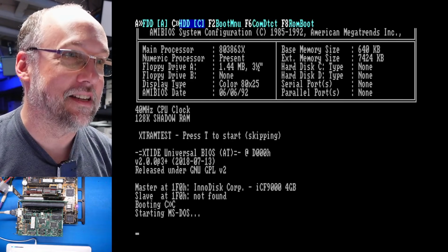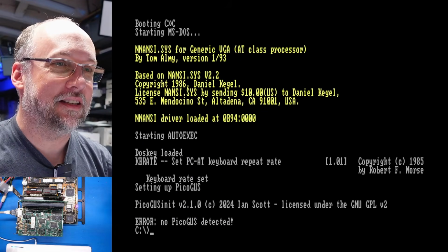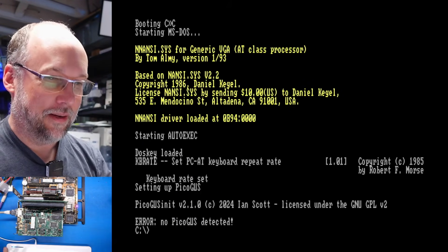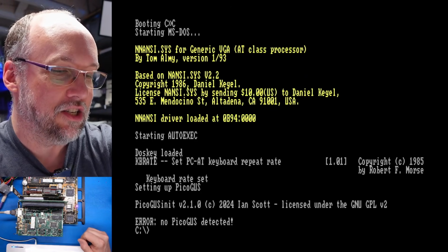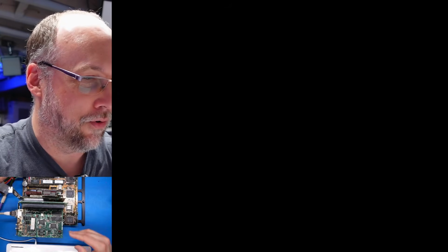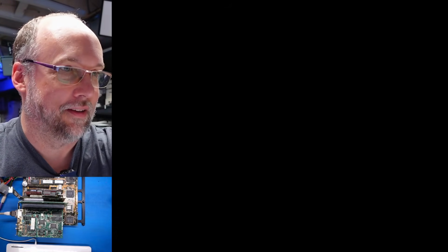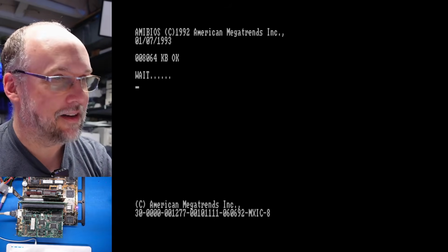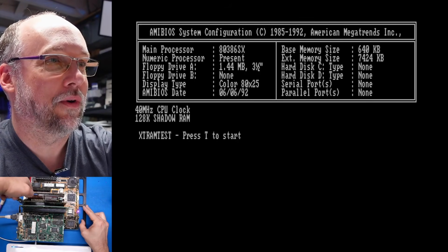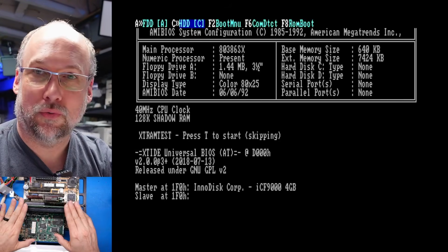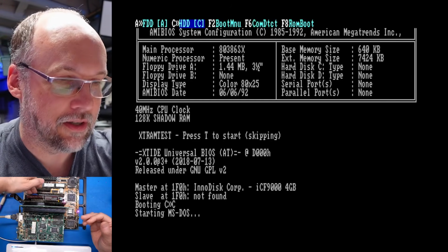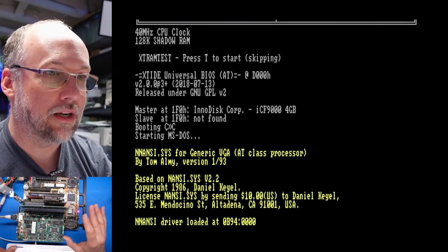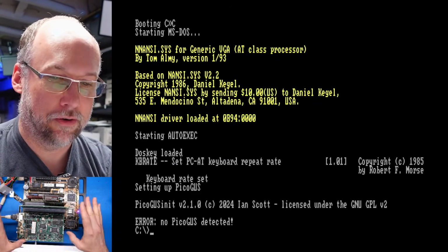So I'm really glad I did that because I didn't want to go to test this STB card and have it not work because of the other issues going on with this whole thing. Let's turn this off and jiggle the cards around a little bit, and we'll just move this stuff back and forth. Let's see if that made any difference. Okay, it's working. Like I said, I'm quite sure it has to do with this motherboard and these slots over here, and it's nothing to do with the riser. It's some electrical issue. And I've just noticed that anytime I put stuff all the way over here, it seems to cause instability on this particular motherboard.